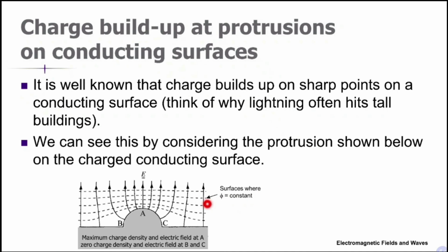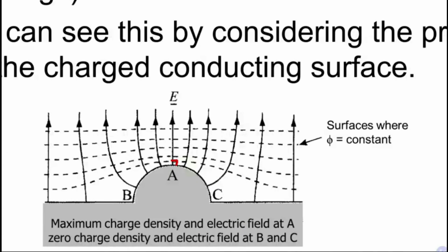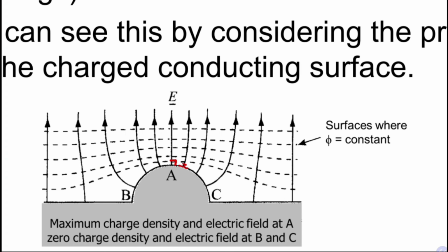Similarly here, if I have a conducting surface, then the electric field has to be perpendicular to the surface. At the top here, perpendicular, and then you have a round surface. If I draw a tangent, you have to be perpendicular to that, and so forth. Our electric field ends up looking something like this, and therefore you can see that at the top, the equipotential lines will be closer to each other compared to on the flat surface.